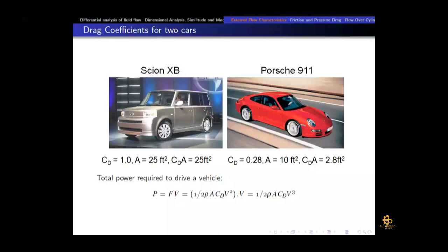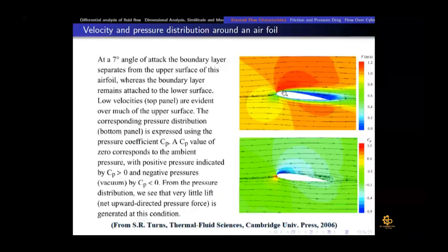Now the interesting thing is this is the aerofoil I was talking about. This is basically the simulation. You can also do it in ANSYS very easily, because I have given you some tutorials in which they have done the flow with an aerofoil. The upper figure shows the velocity. Now you can see there is some blue area. That blue area is where the flow separation is happening, and we have a recirculation region here. So the velocity is almost zero, and because there is a flow separation, pressure is also very low here.